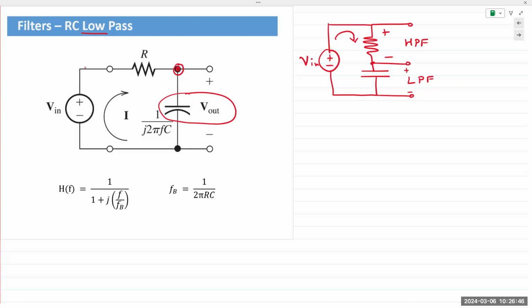We'll first do a quick and easy analysis using the handy dandy table. And then we'll also look at the transfer functions, the mathematical ones. Yes, the voltage VR, V out, would be the high pass. It will function as a high pass filter, meaning it'll only allow high frequencies to pass through. The lower ones will be blocked. So V out, if you take across that resistor, will have a lower voltage at low frequencies. And at higher frequencies, V out would be equal to V in. And we will see that in the graphs and the charts.